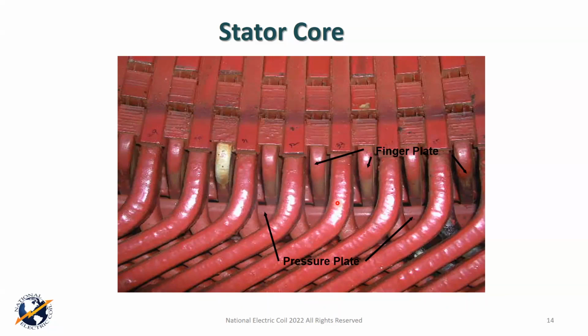All right. And I don't think I have this later, so I'm going to deal with it while I'm looking at it here. A lot of people get confused thinking, well, I've got to repair a bottom coil, I'll take out a couple of tops and I'll be ready to go. Well, it's not that easy. There's a thing called the throw of the coil. The throw is the distance from the top leg to the bottom leg.